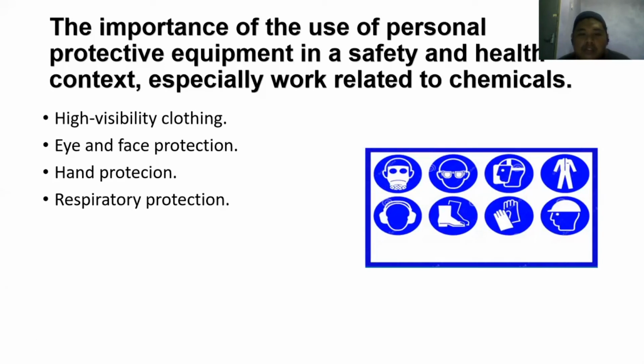Respiratory protection is vital on sites where toxic substances are present. Sometimes what you can't see can hurt you. Respiratory protection like respirators or masks are designed to protect you from dust, fumes, paint spray or pesticides and other dangerous substances that could cause permanent impairment.